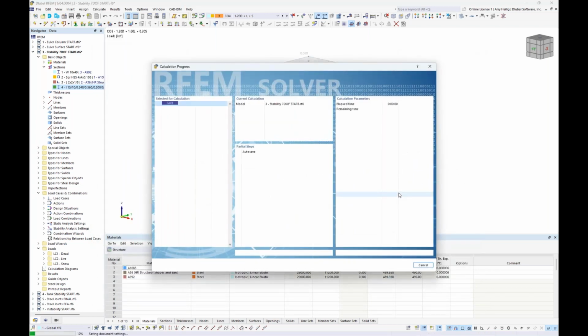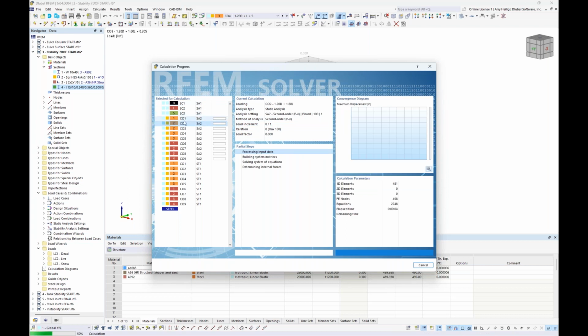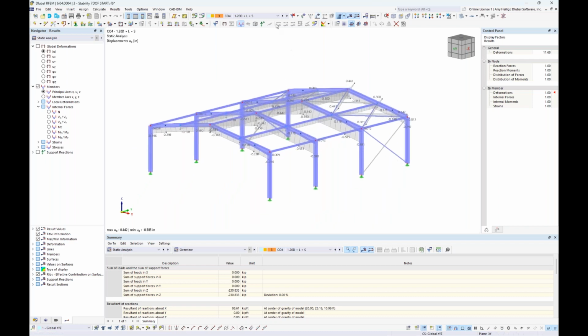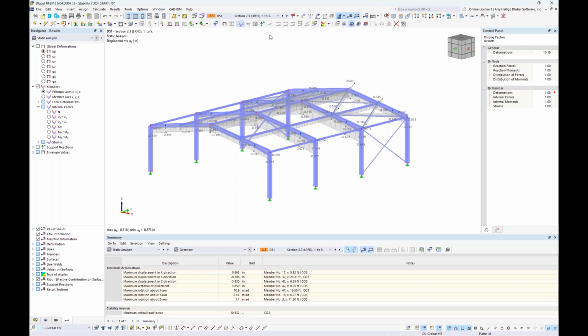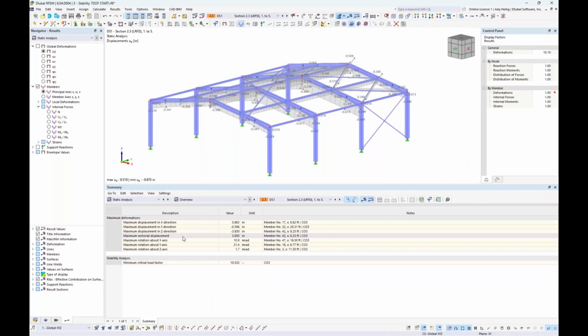So let us run through this calculation by running the Calculate All button. And as we will see, we will first run through the load cases according to first order, our load combinations using a second order analysis, but then we run through all of those load combinations again for the structure stability. So when we toggle this drop down to the design situation for our factored load combinations, again, this is nice because it's more or less an envelope solution for the static analysis. But you'll notice within this table here that shows our static analysis results for this design situation, we have the stability analysis envelope solution as well.